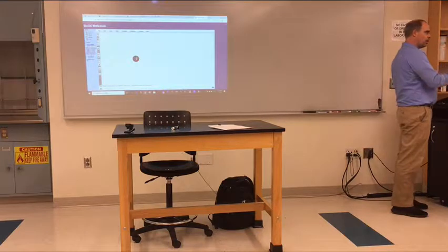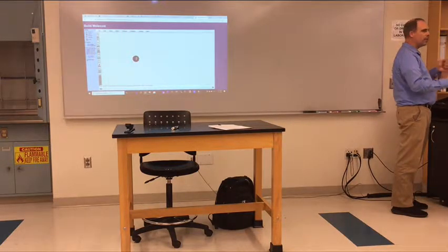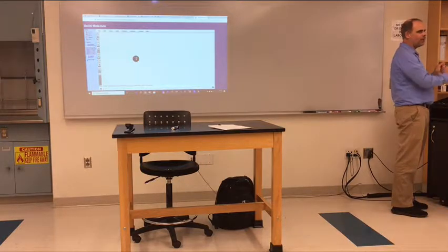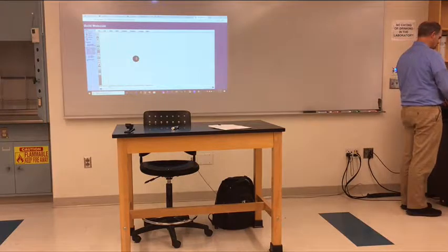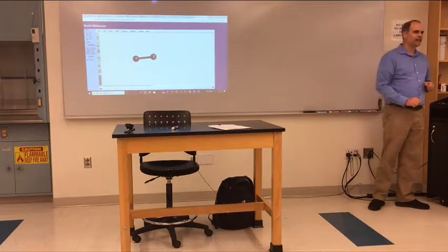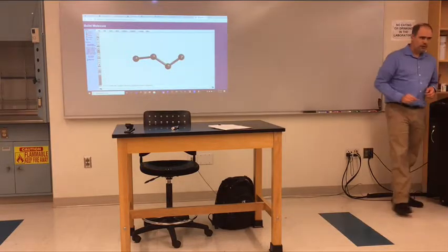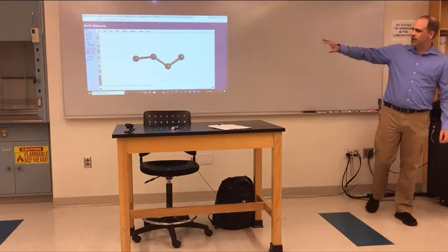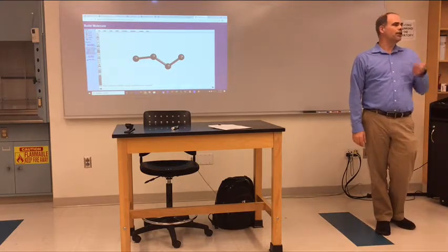If you click on an atom and then drag and let go, it will create a bond to that atom and drop a new atom, whatever you have highlighted. So I can click, drag, let go, and I have now made a carbon-carbon bond adding a second carbon. If I do that two more times, within the program there's a button that will clean everything up for us.